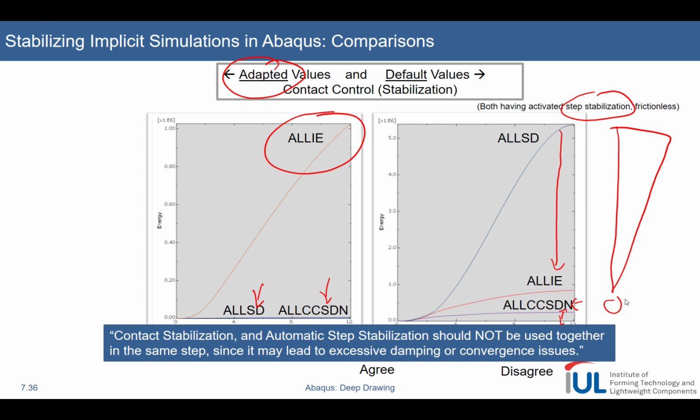So even modern computers having all these fancy hundreds of cores, it doesn't bring much in explicit simulation, because the mathematics and the physics prevent you from using a super nice parallelization approach. So with computers getting faster and faster, but mainly due to many cores being available, not a faster clock speed of your CPU, the long computational time of your explicit simulation remains a critical drawback of this approach.